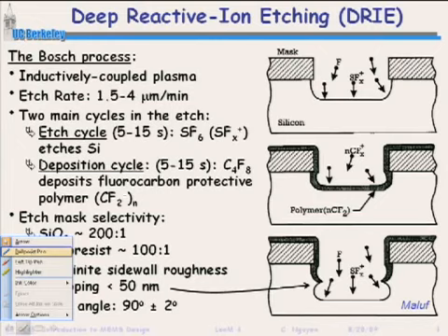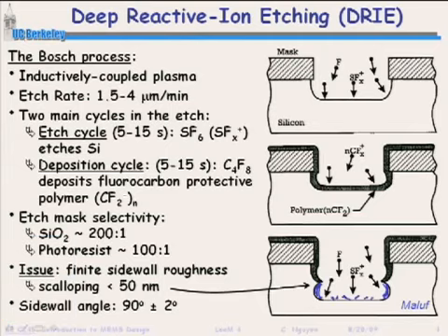And so in our lab, who makes these things? STS makes these things, Plasmatherm. There's a bunch of different companies now that make these. The reactions are similar, but you can have different types of things. You can have things where the polymer can be etched away in some kind of chemistry instead of ions just breaking it up at the bottom. So what you're saying is possible too. There are chemistries that do that as well. But in the end, even this chemistry here will give you a very straight sidewall, so very high aspect ratios.